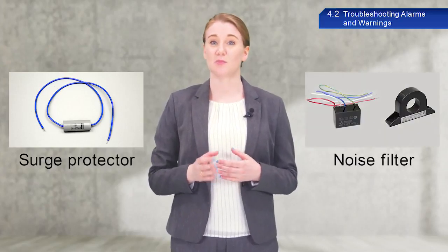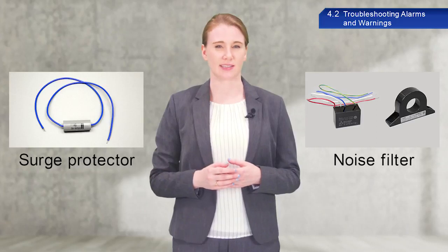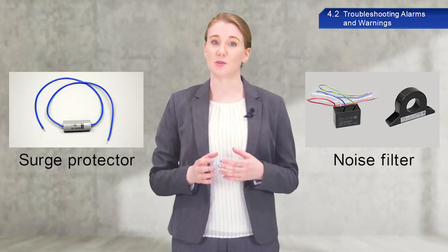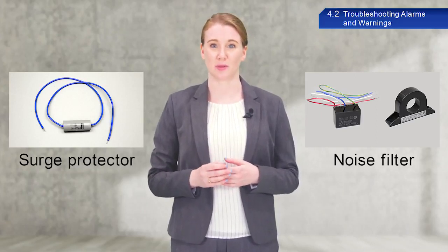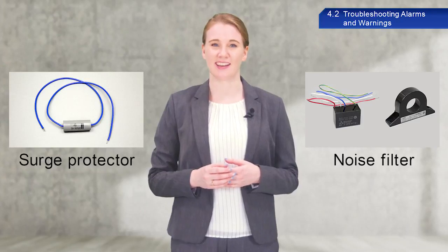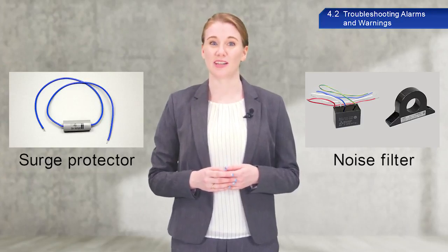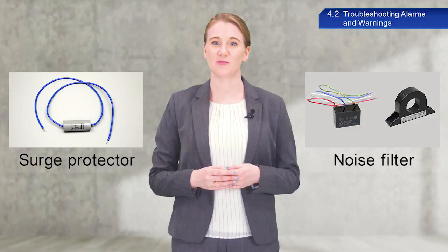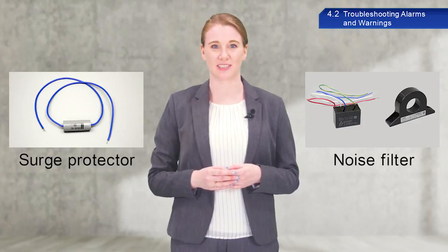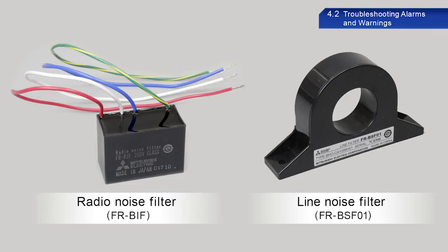If noise generated by the servo amplifier is causing issues, install a noise filter into the servo amplifier power circuit. In this training, you will learn how to install a radio noise filter and a line noise filter. Use either of the two filters that is applicable to the situation when resolving actual noise issues.